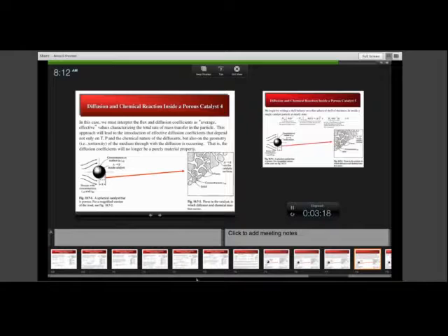And those concentrations will be understood to be averaged over a volume that is small relative to the catalyst particle size, but is large relative to these features that I'm circling here with the pointer. That is, we can define a length scale that is large relative to the local structure in this catalyst particle, but small relative to the global structure. And that separation of length scales permits us to average concentration locally and predict how this average concentration would behave as a function of R.